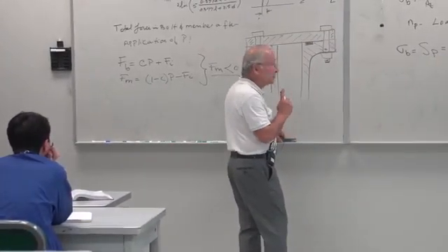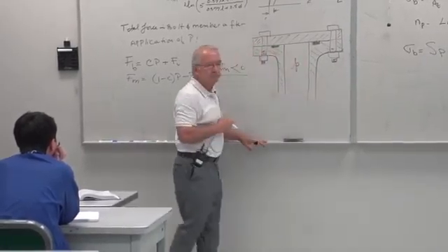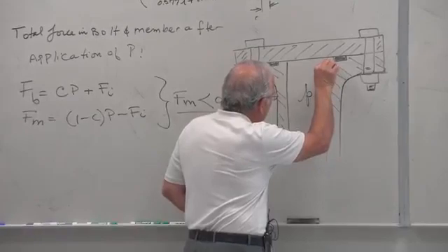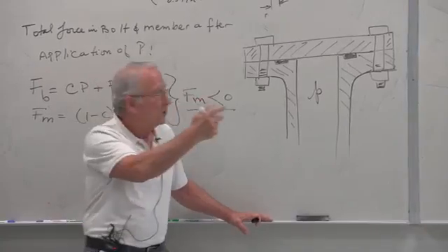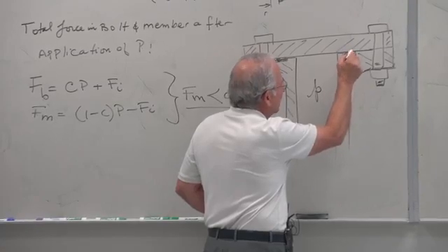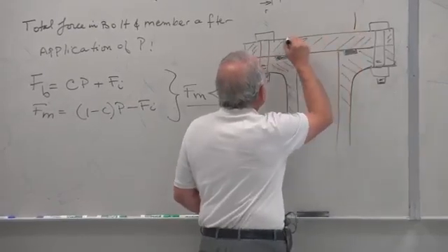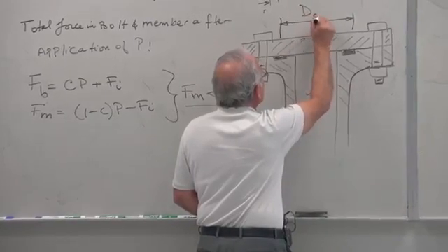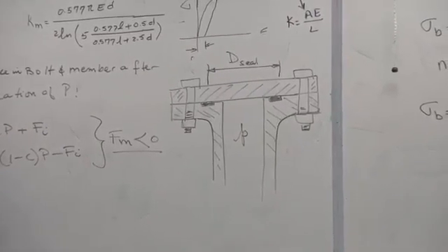So this business about the sealing diameter. If there's pressure inside of the cylinder, then that pressure doesn't stop here, because you have two pieces of metal here. It's not going to stop any pressure. Pressure is going to get in there. There's still going to be pressure here until you get somewhere to the middle of this, not exactly the middle. Sealing diameter is the diameter for which the pressure is confined. It will not escape past that.